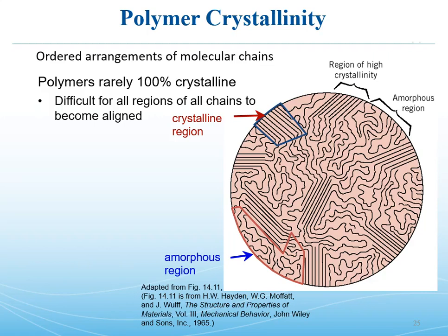So there's certainly plenty of opportunity for those crystalline regions to move relative to one another, because the chains in the amorphous region can move much easier, slide past one another, so you can actually start displacing and rotating those crystalline regions around as you start applying stress in a given direction, especially if you apply a little temperature.